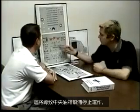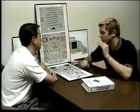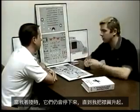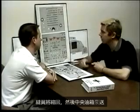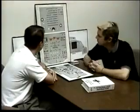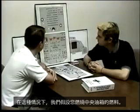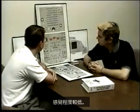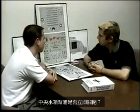This will cause the center tank pumps to stop running. When I land, they'll still be stopped until I bring the flaps up. The slats will retract, and then the center tank pumps will again be able to run. In that scenario, let's assume that you burn the center tank fuel. It sends low level. Did the center tank pumps shut off right away?